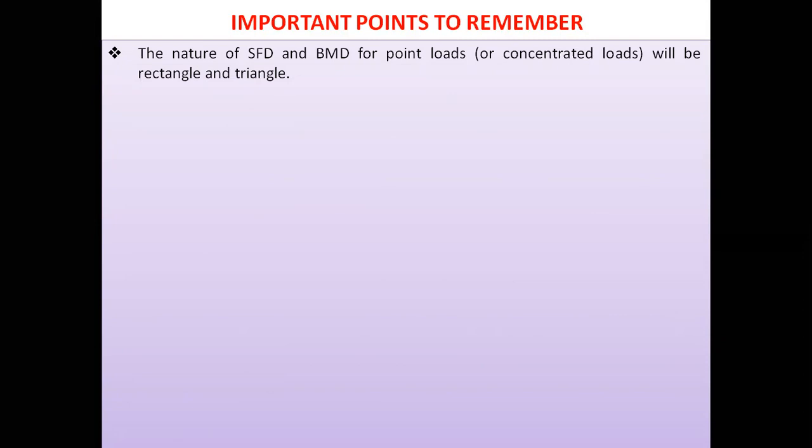I'll explain what this rectangular shape and triangular shape are while plotting the diagrams. The shear force between any two point loads remains constant. I'll tell you what is happening while plotting the shear force diagram.